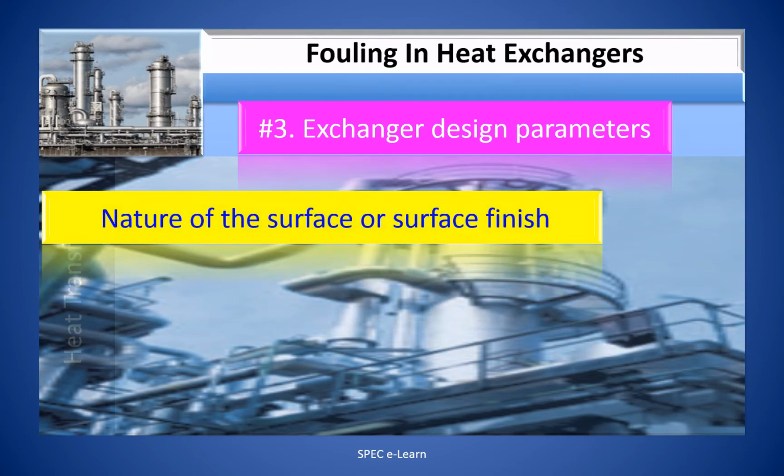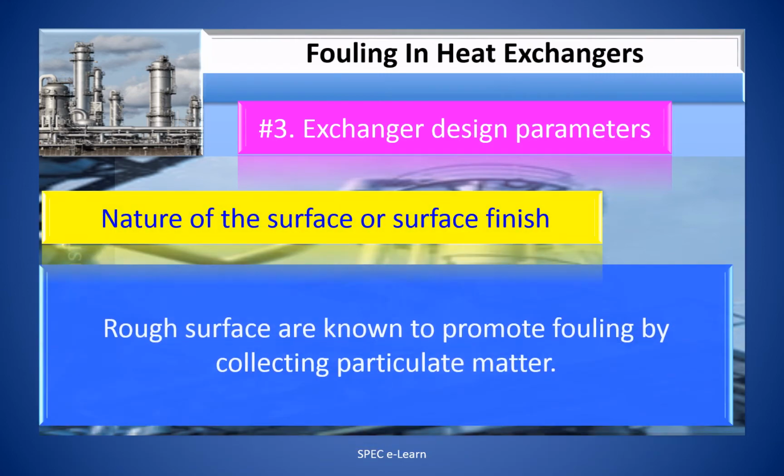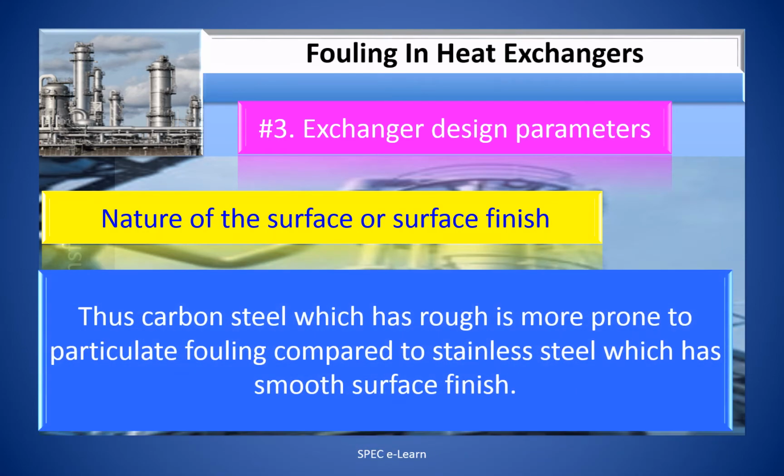Nature of the surface or surface finish. Rough surfaces are known to promote fouling by collecting particulate matter. Thus, carbon steel is more prone to particulate fouling compared to stainless steel, which has a smooth surface finish.